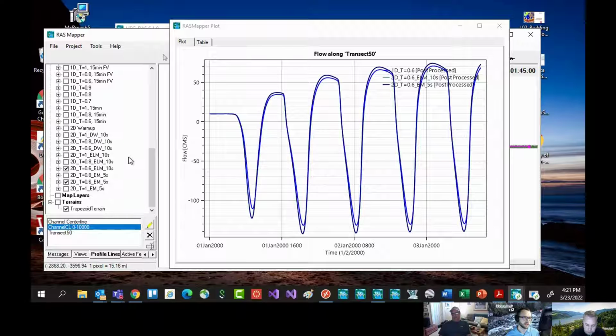Mm-hmm. Chris, did you include Coriolis in any of these simulations? I did not. But in theory, if you were modeling a larger bay or river confluence with the ocean, that might actually be one of the few situations where it's worth turning that on, right? I'd love to hear what Gary has to say about that. The answer is yes, but I would also qualify that it's more so true if you're farther away from the equator, right? So if you're up in Alaska, Coriolis might be an important parameter to turn on. Understood. Yeah.